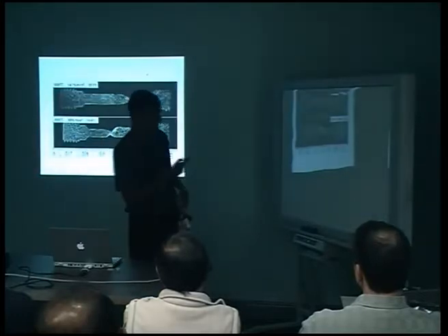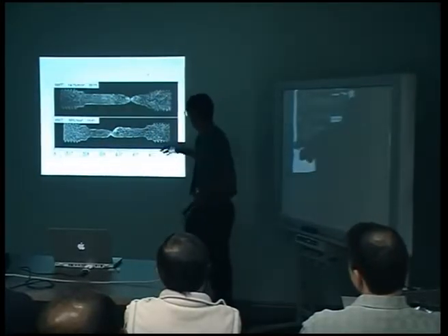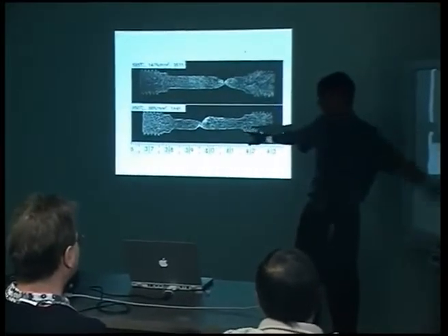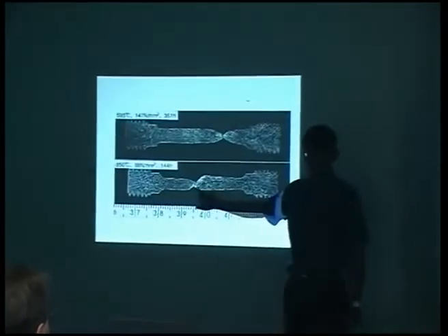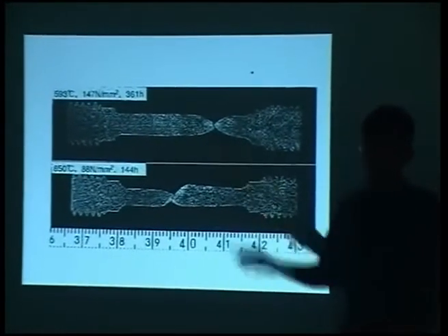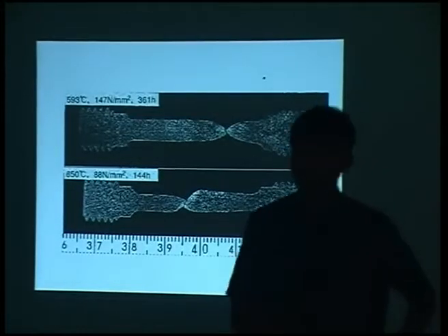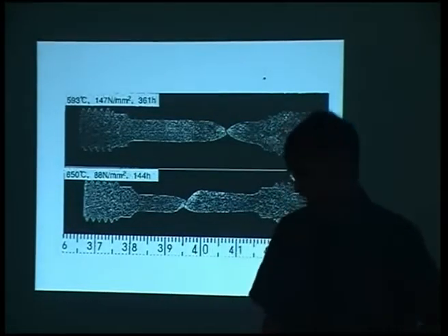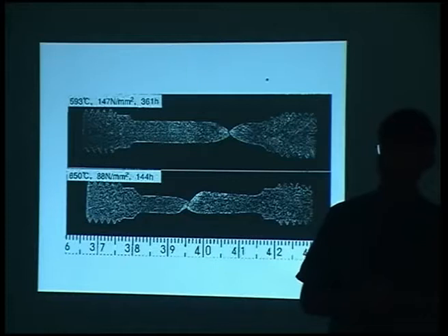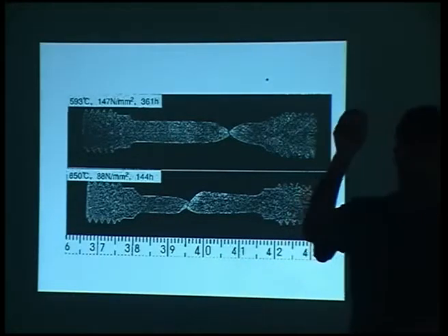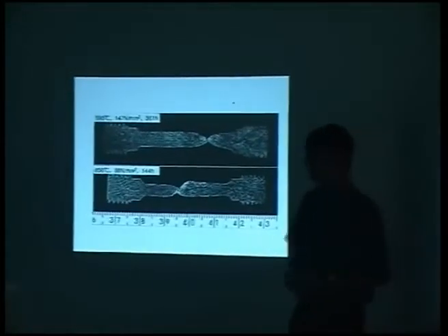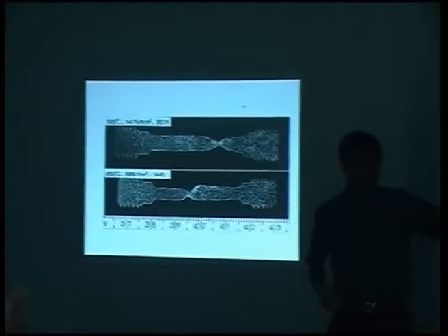And that's illustrated in these, which are just taken from the literature. So this is a case where it's failed in this inclined manner. You can see the creep specimen has failed by a type 4 mechanism, whereas this is how it would normally happen if it failed in the parent plate. Now there is no method of predicting the failure stress. So let's assume that for the parent plate we can predict the creep rupture strength, because I've already shown you models where we can do the creep rupture strength as a function of something like 50 variables. How do we decide what's going to happen here?